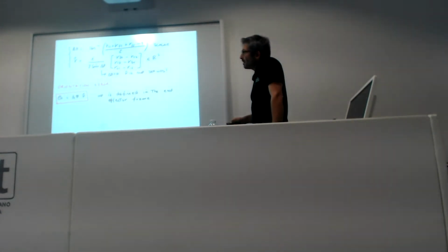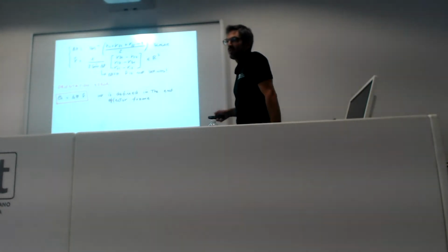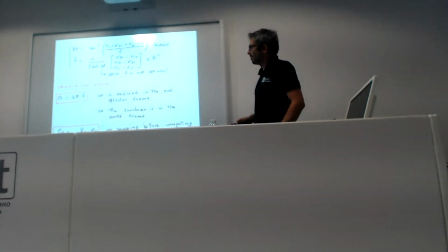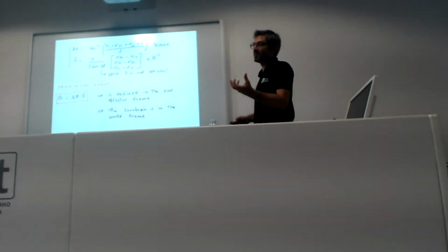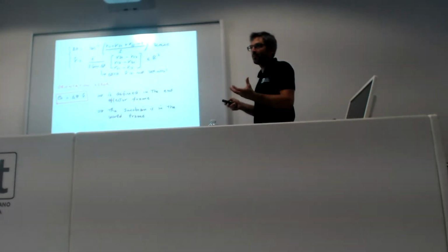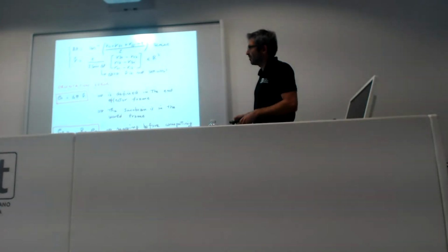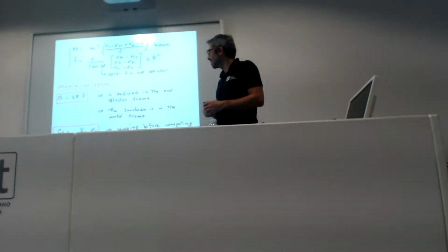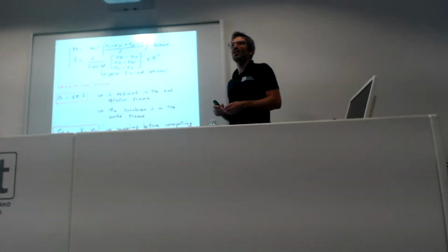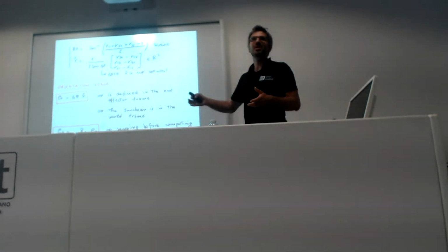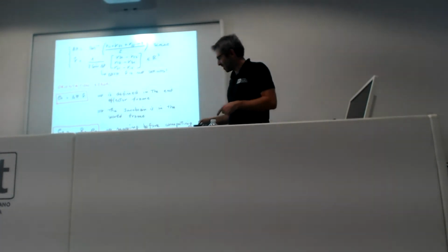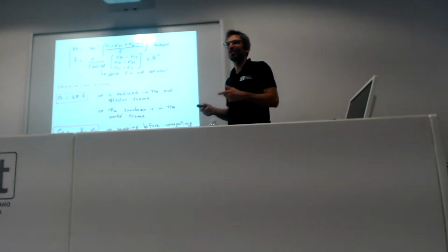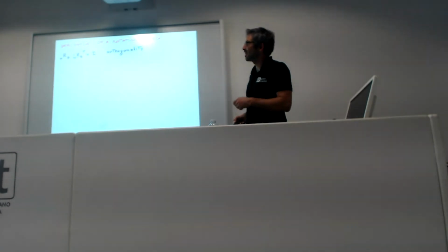We also need to take care that the orientation error is defined in the end effector frame. So if we want the moment expressed in the world frame, let's say because we are doing everything in the world frame, we need to rotate it properly before computing the moment. Actually, in the second lab I prepared, there's an exercise on the orientation, and I saw that everything was unstable and I didn't understand why, because I forgot to put this rotation before mapping to torque. Okay?